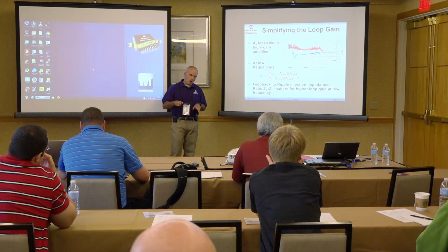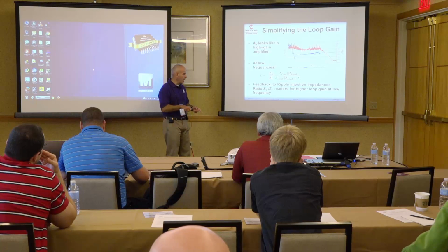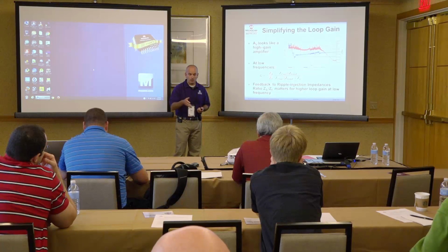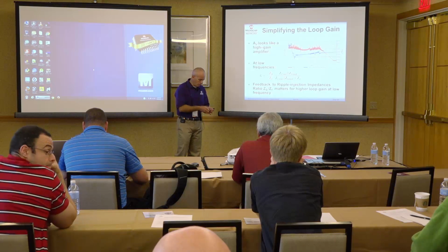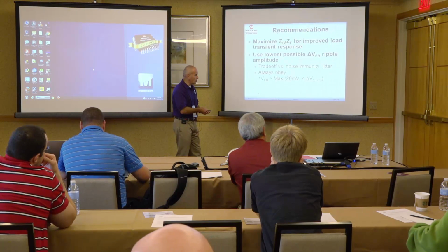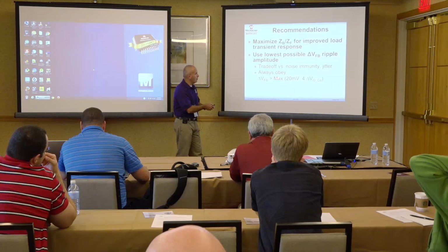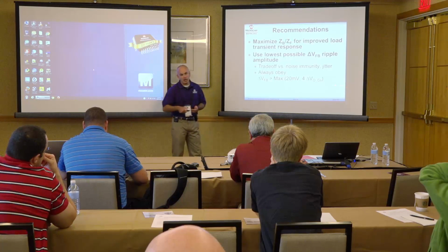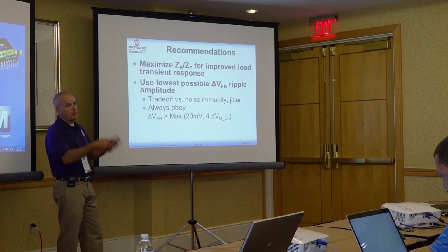The minimum might be dictated by the theoretical limit for stability, but also, because the control is ripple based, by other factors like jitter or noise immunity.